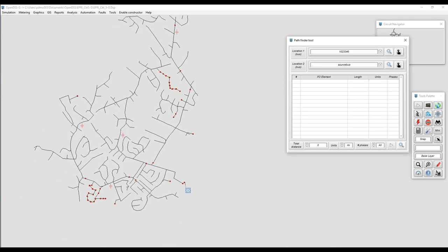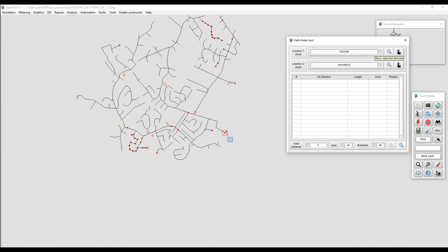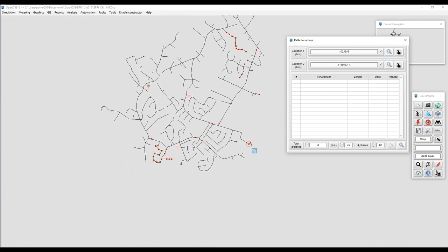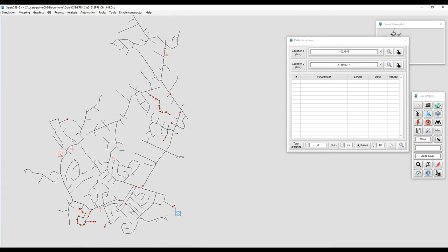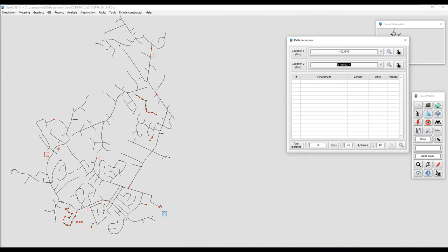To specify the names of the buses we want to link, or check the distance in between, we can specify the name. The names are provided on a list that populates itself if you start writing the name, if you know the name. There is also a magnifier tool that will locate the bus within the GUI in case we need to check the location.